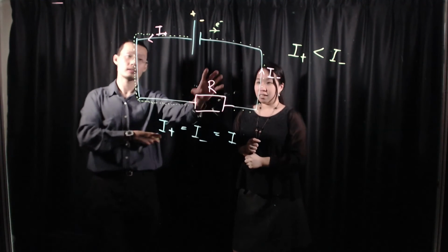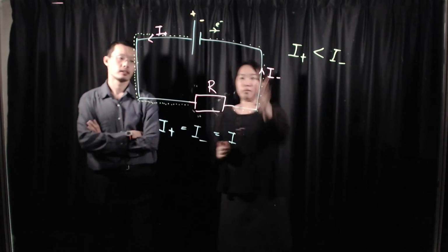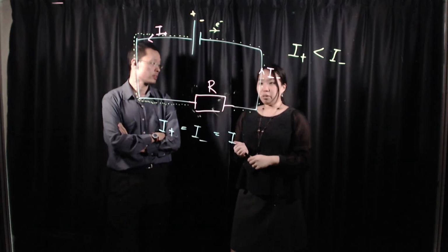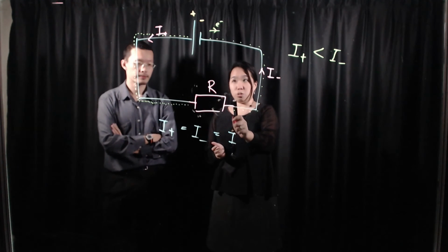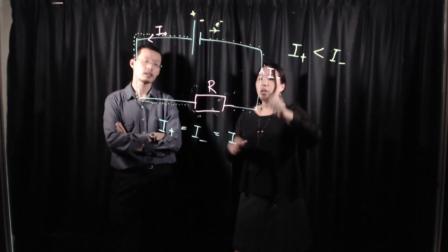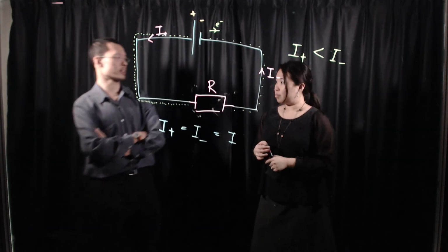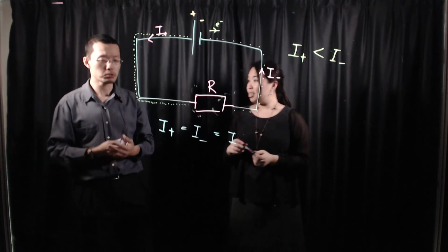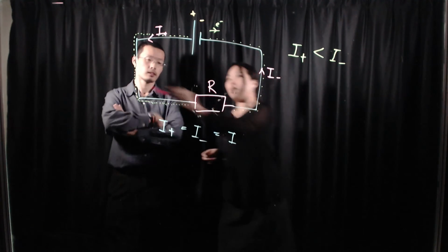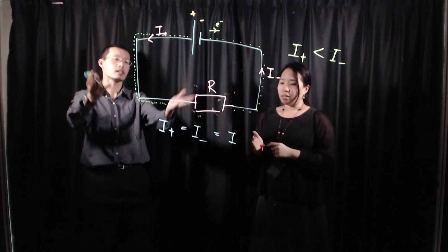You have to think of the whole circuit, because it's all connected. You break any point, and the thing behaves differently already. So the resistor controls the current throughout the entire circuit and not just after it. Current isn't used up. How do you use up current? You can reduce current, you can increase current, but it doesn't reduce the current afterwards. It has to be the same throughout, in this simple circuit at least.